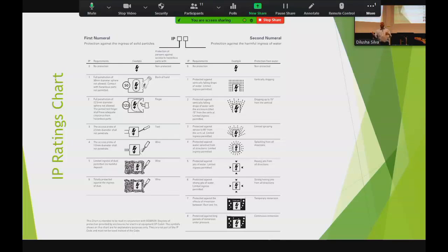So when you're designing something, you're designing a box, contact or a controller, you need to factor in things such as, what's the IP rating? The IP rating of a PowerPoint is IP 21. Okay? A light switch would be 44. And it's all about what you can touch when it's in service. All right?